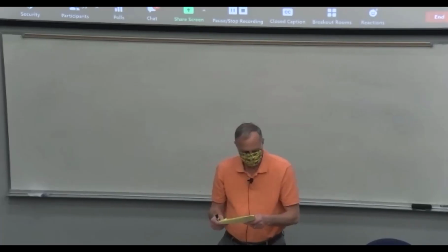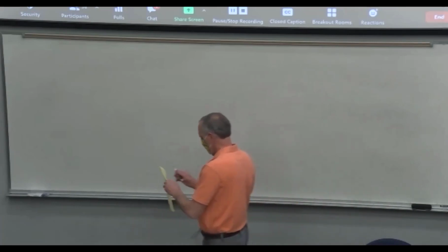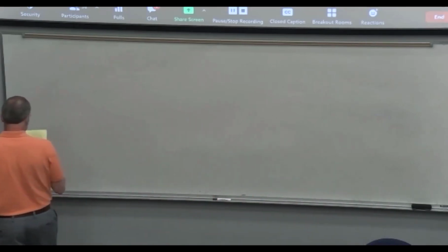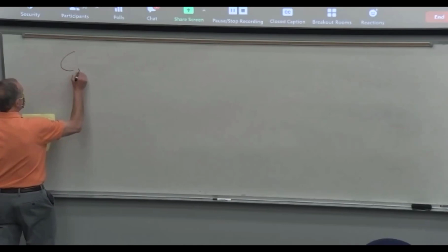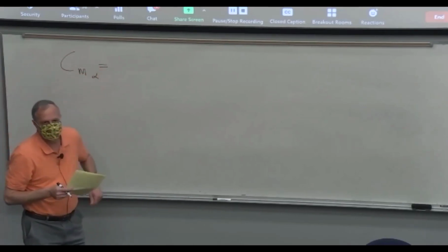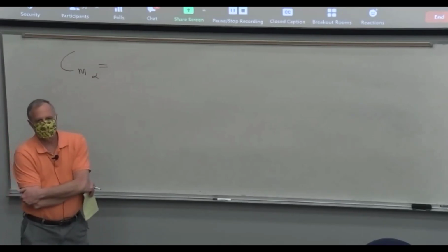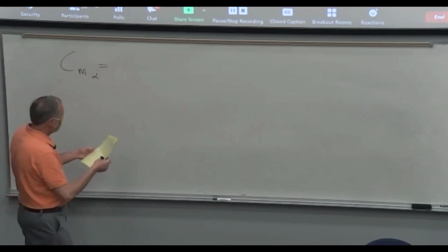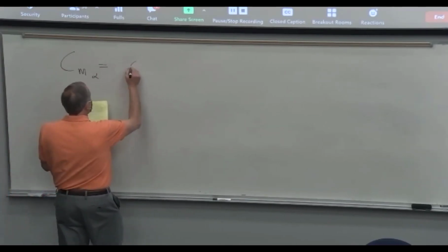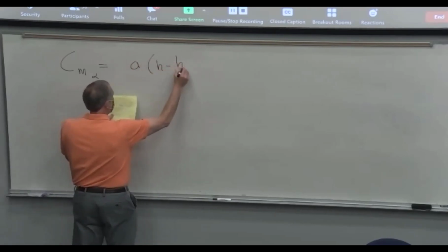We're going to continue with where we left off about the neutral point and the static margin, which we need to define today. So where we left, we had gone through and calculated the total pitching moment, split it up into stuff that multiplied angle of attack and stuff that didn't. The stuff that multiplied angle of attack we called Cm alpha, and that's the stability parameter that we look at for pitch stability.